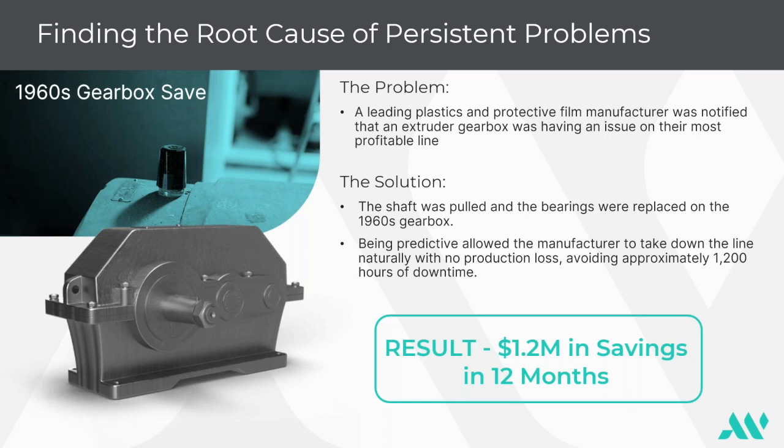We started monitoring this thing, and we were able to detect within the vibration data what a lot of people call rotating looseness. Some people call it Type C mechanical looseness, where essentially you have a lot of turning speed harmonics that come into play.